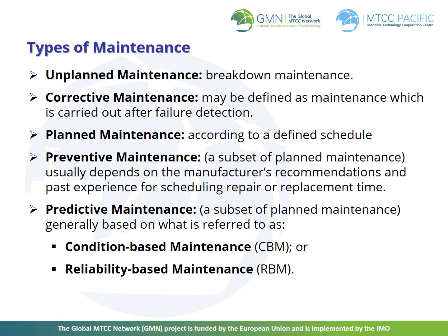Planned maintenance. Maintenance scheduling or planning embraces all activities necessary to plan, control, and record all maintenance operations. Planned maintenance is based on a defined schedule of equipment maintenance. This maintenance is usually defined by the majority of shipping companies. The planned maintenance schedule is decided based on manufacturer's recommendation or use of analytical techniques such as analysis of mean time between failures, or MTBF, and reliability analysis.